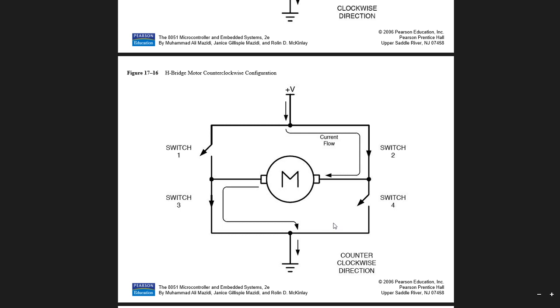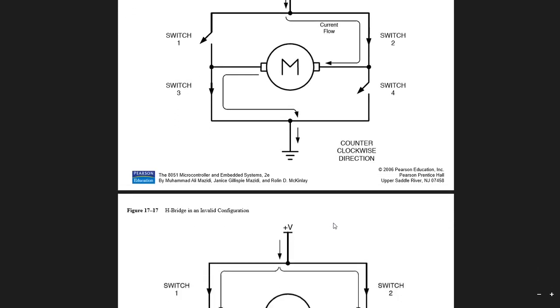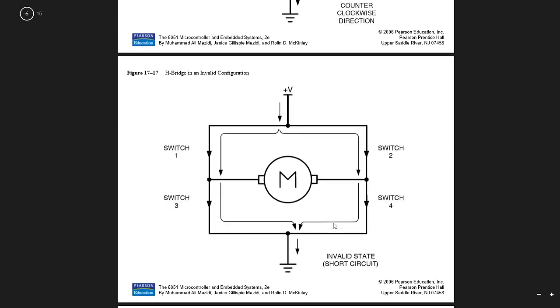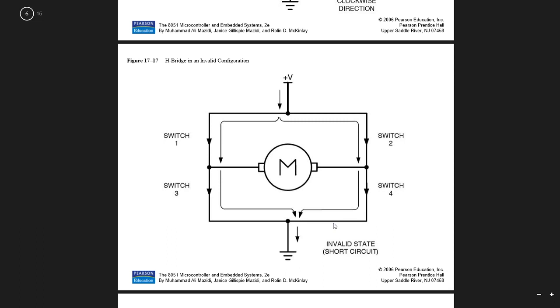But again, I am telling you, this is not the way of connecting a DC motor. This is not a practical way, just to make the concept. And if you close all four switches, this is for sure invalid and a short circuit.